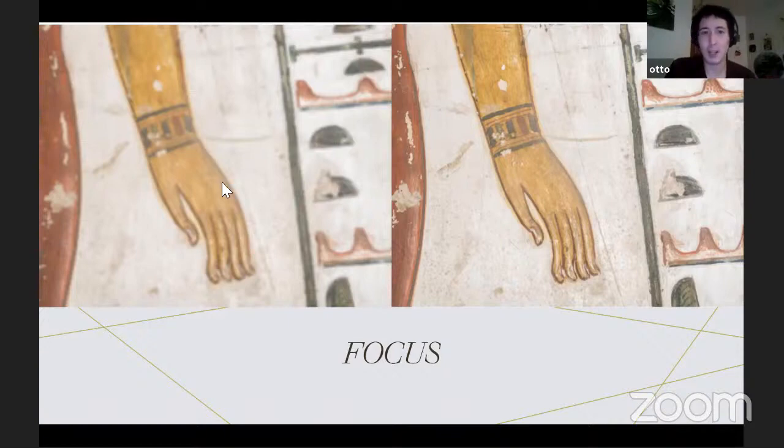The software can actually recognize these out of focus images, but it returns a lot of false information from them because not everything is sharp. What it's doing is detecting features such as these cracks on the hand. As you can see in the out of focus image, they're barely visible, so it won't return good information. So you should generally try and keep every photograph in focus, or delete any photographs that are out of focus.